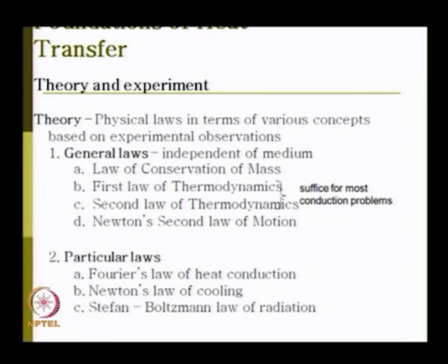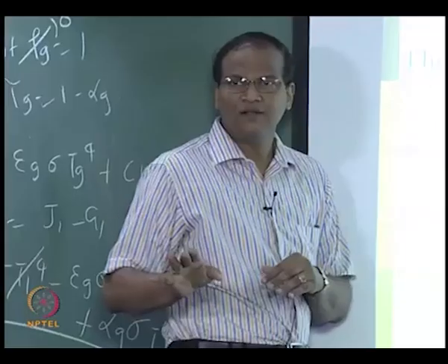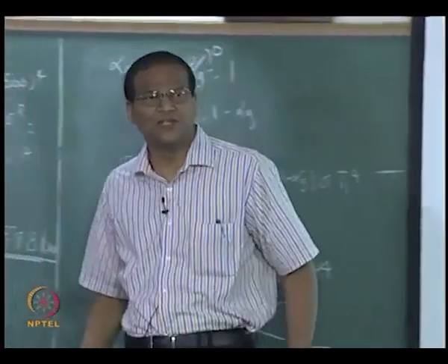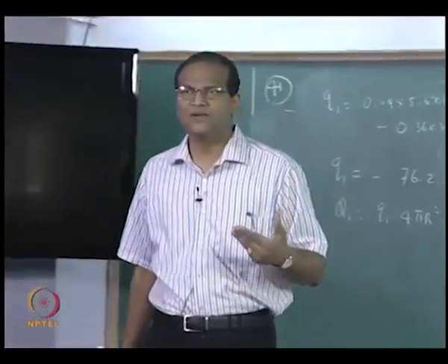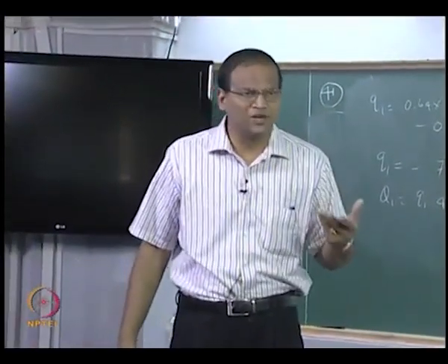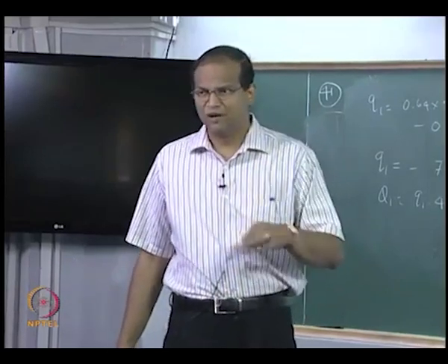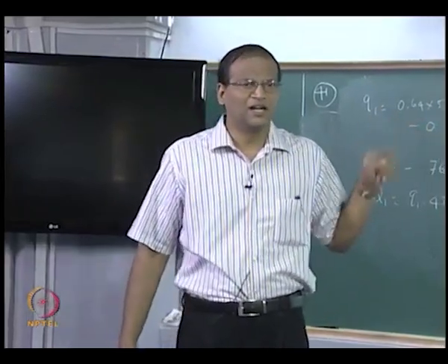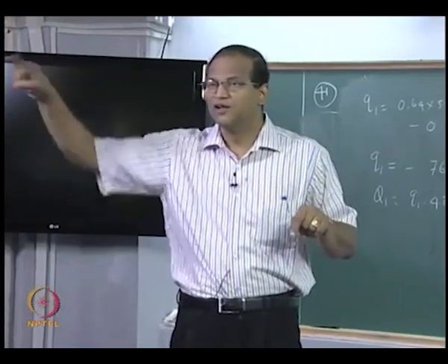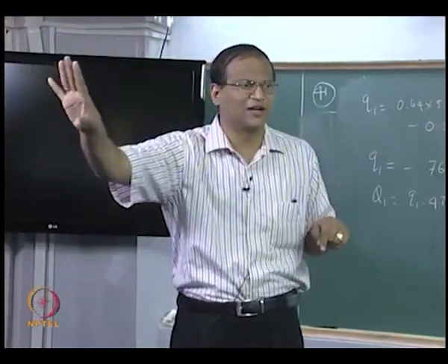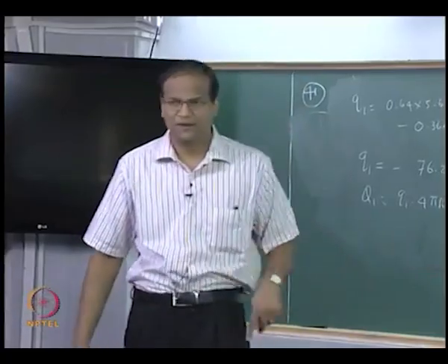Please remember that the equation of transfer is not an energy equation. Even in the problem which we solved in the last class, there is no equilibrium there. That means the RT equation is not a standalone equation, it gives rise to a source or a sink, right. So it has to be solved in conjunction with the equation where some property is conserved. Are you able to appreciate? So in a combined conduction radiation problem you have to solve the conduction equation, there will be a source term for radiation. If you want to calculate that source term, you have to stop the conduction calculations and do your radiative calculations and go back.